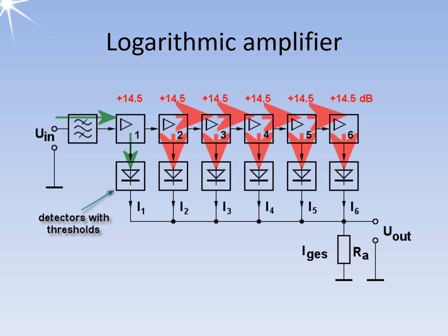Detector 3 causes the output to continue to increase after the second stage is saturated. The overall gain decreases as each stage saturates, but some degree of gain is still available. Proper selection of the IF stage's gain and saturation points results in an approximately logarithmic response curve.